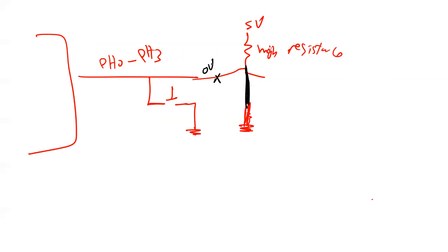So if I press the button, it's not going to have any impact because this is 0 all the time. You got what I'm saying? Because you connected this one. That's why this one has no impact. The push button has no impact because it's 0, and there is no way to know where the 0 volt is coming from. There's no way.